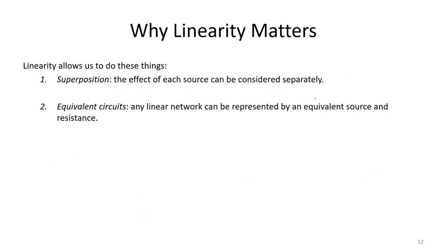So why does linearity matter? We're going to see in today's class that circuits having linear behavior allows us to make some very important tools. First, linearity allows us to use superposition. We'll see later in this video that it allows us to consider the effect of each source separately. We can add multiple sources together to determine what the cumulative effect will be. The second thing linearity allows us to do is to use what's called equivalent circuits.